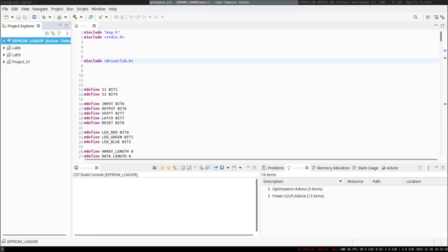Today, I wanted to make this video to share with you a solution that I had to find for Driverlib inclusion for this project. When you install CCS or Code Composer, it does not automatically include the Driverlib header and subsequent headers and source files. So I wanted to talk about that and share with you my solution, as I needed to use them for my project.